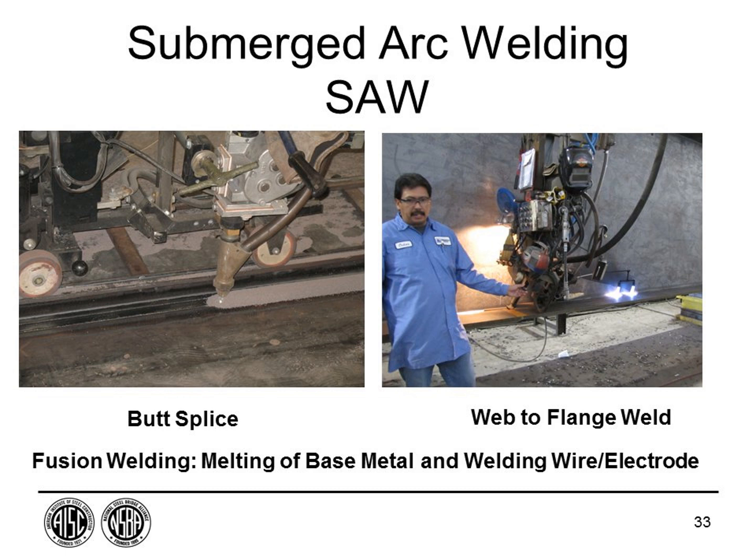So what we need to do is have a steel that doesn't harden easily, and we need to control that cooling rate. Part of the way to do that is with some preheating. This shows a preheating torch at the front of the welding process where we're preheating the flange, in this case to eliminate any moisture, but also to increase its temperature so it cools slower. And if it cools slower, we likely won't form martensite.